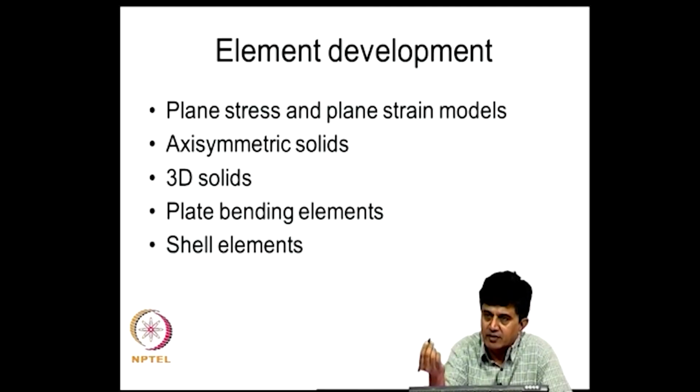Then the questions of coordinate transformation, assembling, imposition of boundary conditions, and calculating external nodal forces will have to be addressed, thus deriving the final equilibrium equation.